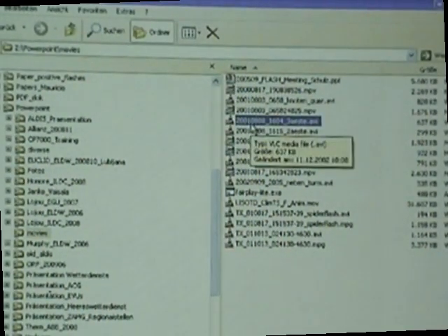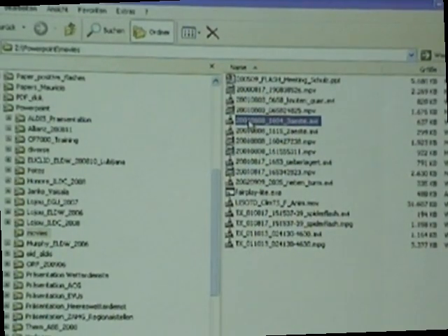Just a question. If this was a positive flash, is the scintillation of the light divided into a heavy component or strokes? I think 99% of the flashes that we have start with a positive upward leader, so they are negative flashes in effect. Afterwards, negative return strokes, negative subsequent, and also the alpha pulses are negative.